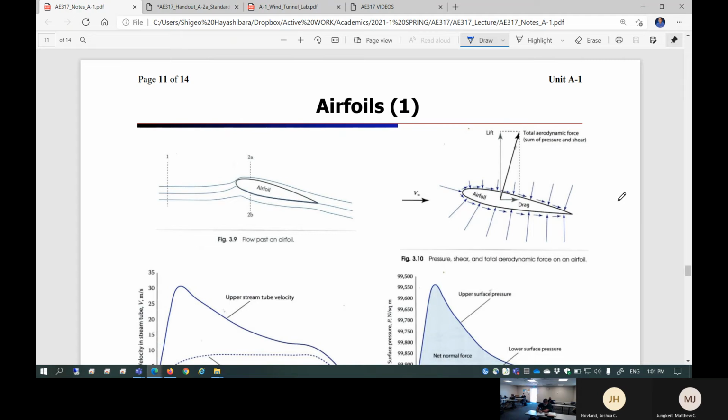If you want a low speed, high capacity, payload type of airplane, such as a firefighter, you're not going to choose a certain cross section, of course. You're not going to choose an airplane like the one sitting next to the bookstore, right? That airplane is a horrible airplane for low speed. And then, of course, a high-speed airplane is completely opposite. But some airplanes in the transonic region actually have a fairly thick cross-section, a supercritical shape. So there is lots of information when you choose the cross-section of an airfoil.